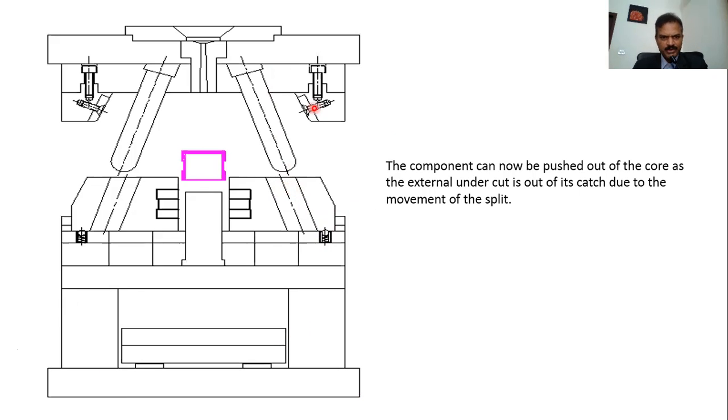And one extra thing you observe here is we have put another small wear plate here, which you can play on for fine tuning adjustments, right? And also once it is worn out, you only need to change the small little plate or shim it out to the right dimensions. Yeah.